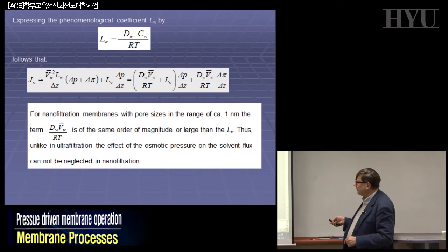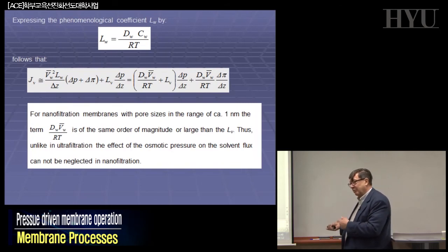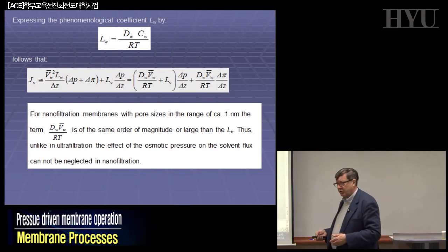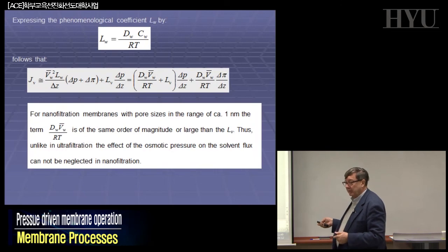Now, in nanofiltration, where the pore size of the dense skin is of the order of, sometimes lower than, 1 nanometer, very small, this term is telling you that we can have significant rejection also for species such as magnesium sulfate. Not only the monovalent, but particularly the bivalent will be rejected. All the amino acids, sugars, and a lot of other compounds present in a lot of industrial production will not go through the membranes at all.